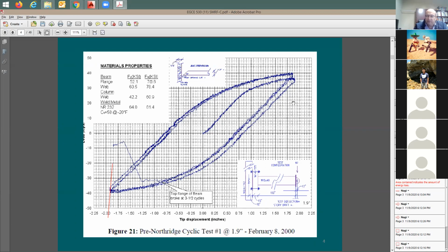Ductility factor? Special moment frame, is it 8? Now, I want to hear for a special moment frame. Yeah, for a special moment frame, this is going to be the one that you like to use. But when you look at this one, look at the yield point. Compare this yield displacement with this ultimate displacement. How much is this factor here?